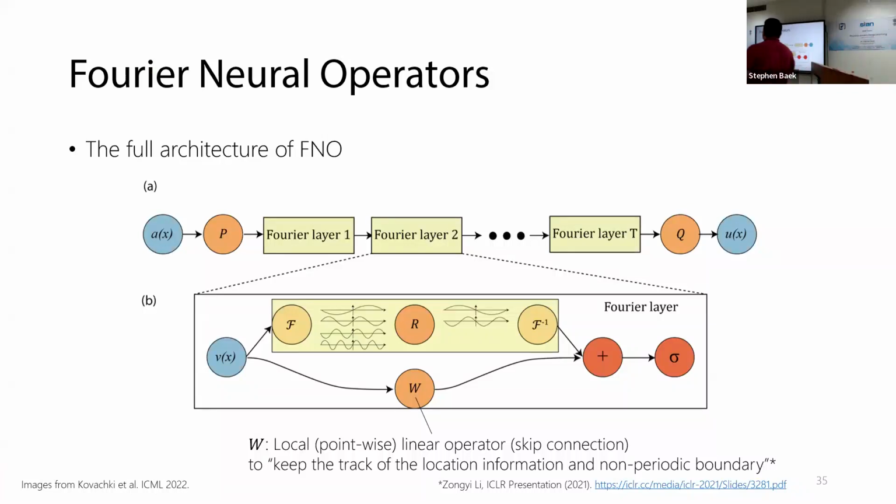Yeah, this part over here, this yellow shaded box, is what we're going to implement. And for convenience, we're going to just call it a spectral convolution layer. So recall what we just learned before the break. We first do the Fourier transform, right? Forward Fourier transform, decompose into the frequency components, and then compute some linear transformation of the frequency components. And as a result, we get some transformed signal. And then we're going to be applying the inverse Fourier transform to generate the output.